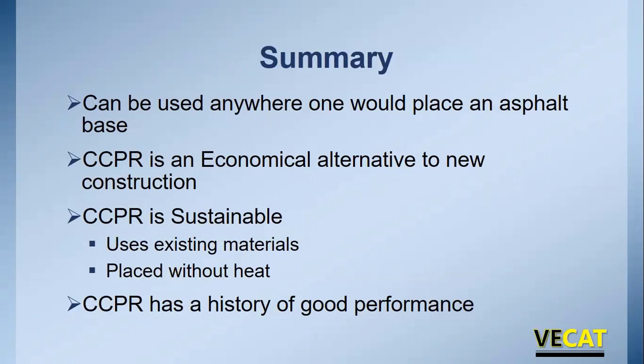So in summary, kind of an overall background of CCPR, but really CCPR can be used anywhere where one would place an asphalt base mix. CCPR is an economical alternative to new construction. It is very sustainable. We're going to use the material you've already bought and paid for. So we're going to reuse existing materials. We don't have to go quarry out new materials, and we're going to place it without heat. So it's a very green process. And finally, CCPR has a history of good